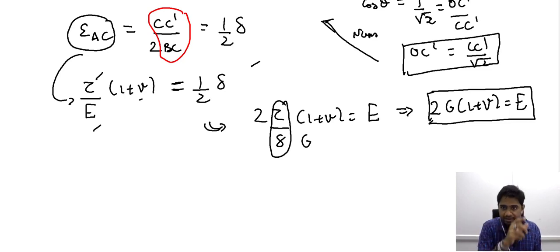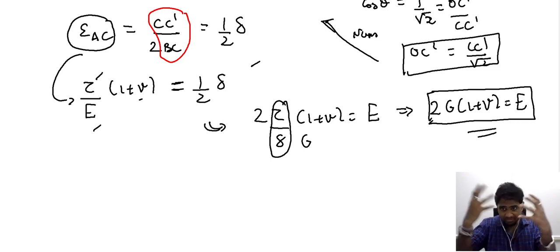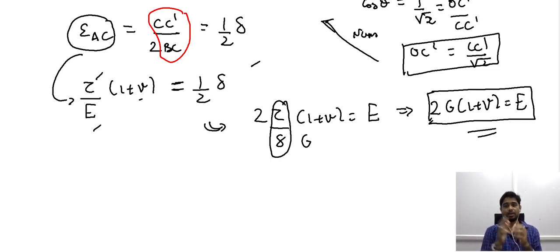Once we have arrived at the strain along the diagonal element, we move back to our original sample and attempt to quantify the shear strain with respect to the element that we are interested in, because we need to relate these two. We arrived at an expression for the shear strain based on this element, and using that we were able to arrive at this rather straightforward looking expression. But these are all the steps we need to take to arrive at it.